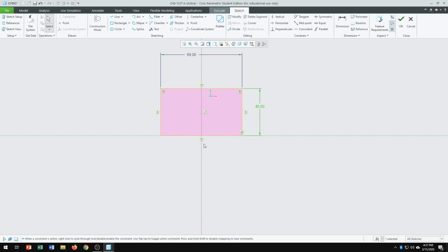And one thing as a preparation, we need to give a dimension from this edge to the center line, 50, that later on we're going to use as a plane, the right side plane, on which we are going to place a rib, using the rib profile.